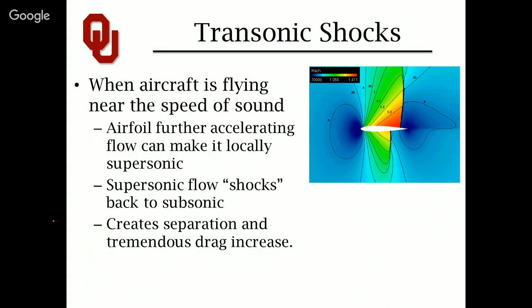But then the bad part happens. Then the world comes crashing down. Physics comes crashing down on top of your head. At the overlapping black lines at the aft portion of each one of those supersonic flow regions, that's where, due to the basic shape of this airfoil, due to the flow acceleration imposed, due to the thickness of this body being pushed through the two-dimensional flow case, you create a shock wave. The flow no longer expands, and you create a discrete shock at the back side of those supersonic flow regions.